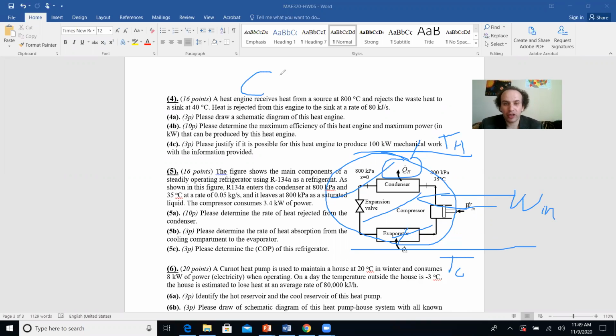And you have the coefficient of performance, which will be what? Which will be QH divided by work input, and it will be QH divided by QH minus QL. I'm sorry, I made a mistake here. It's not QH, it's QL, because you talk about a refrigeration cycle. I also make mistakes. It's okay. The key point is that you don't make mistakes, okay?